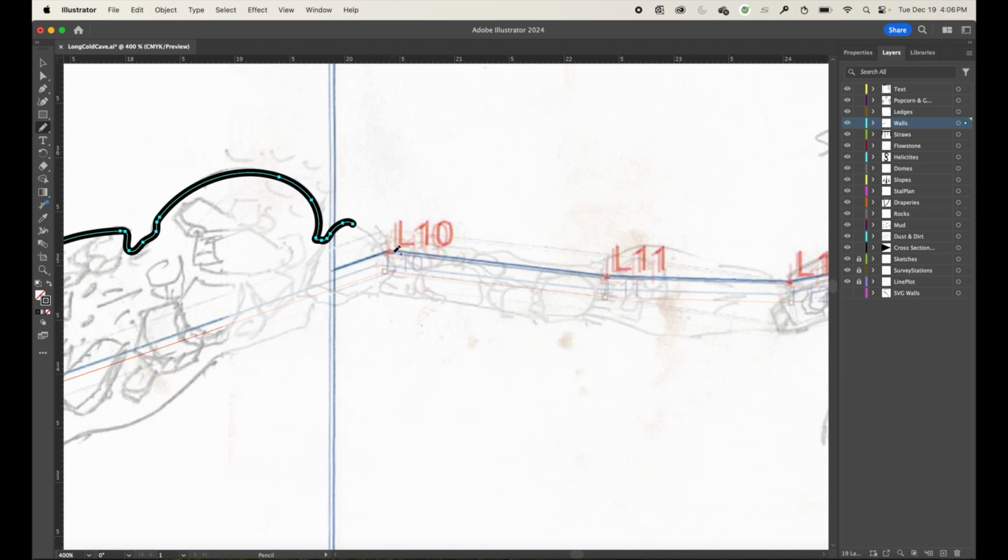You might have some where the angle is just slightly off. And so when that happens, as you're drawing along, you're going to need to continually adjust. Usually you're rotating or scaling your sketches so that they line up with the line plot that you imported from Compass in the SVG file. So let me show you how you do that as you're going along.